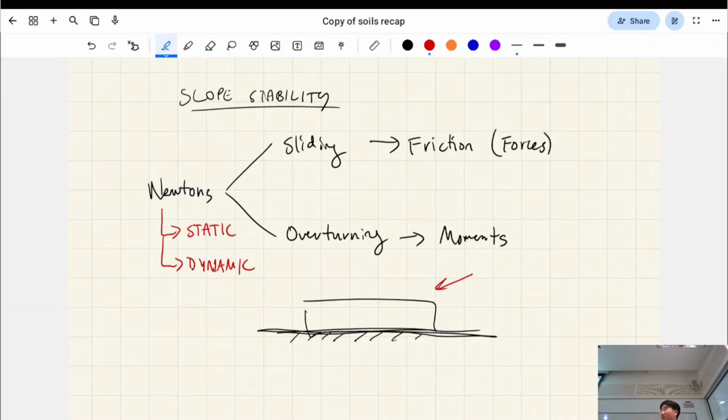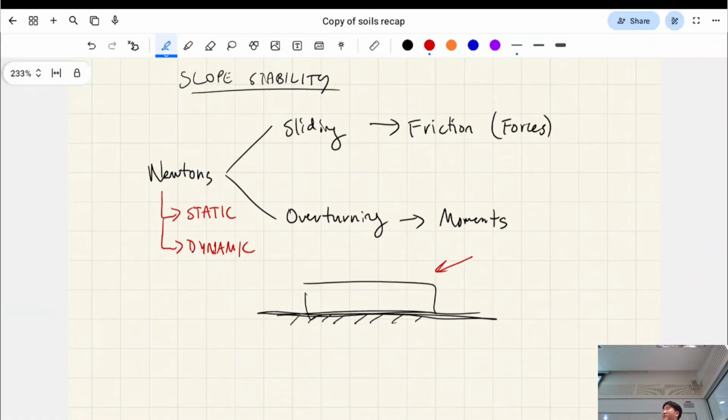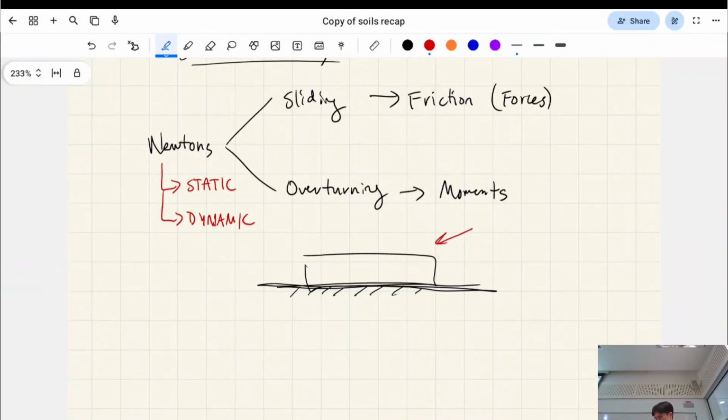That's what stability is about, or that's what instability is about, right? So if I'm pushing against this concrete slab and it starts sliding, that is a sliding stability failure, right? I'll give you another example. Same concrete slab, and it's teetering over this edge, maybe like this. And it falls due to the wind. That's an overturning failure. That's a point of rotation.